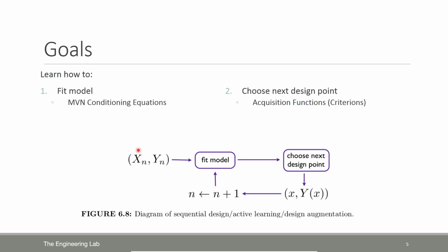So now, number one, the first goal is to learn how to fit and construct your surrogate model. The second goal is to help construct the acquisition functions. The acquisition functions help you pick the next candidate point of your finite element model. Ultimately, when you have a firm understanding of 1 and 2, making sense of the final machine learning algorithm is pretty straightforward. Basically, you start off with training data. This training data is used to construct your model or your surrogate model. Your surrogate model is used to construct acquisition functions. These acquisition functions are used to yield the next candidate design. Once you have this candidate design, you then run your FE solver. Here we're using Nastran.